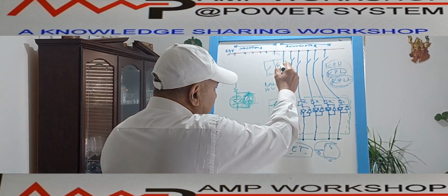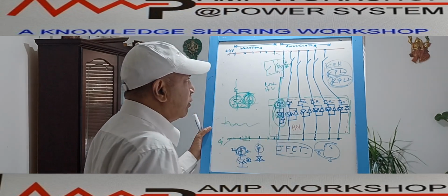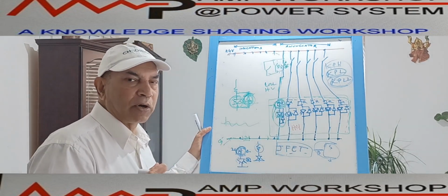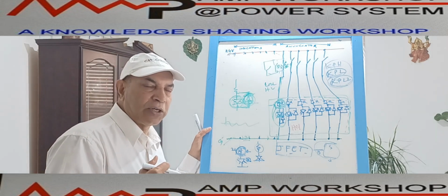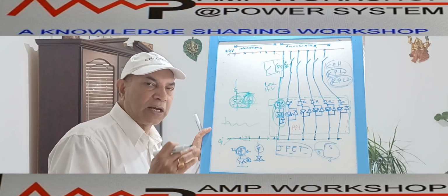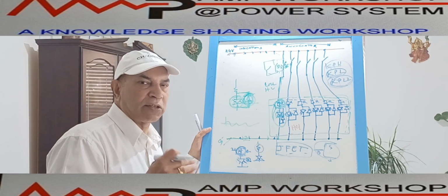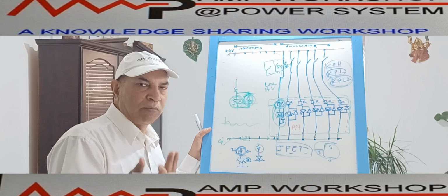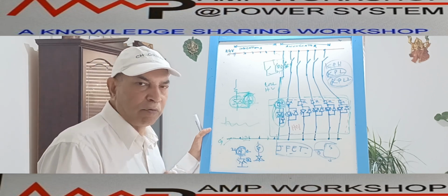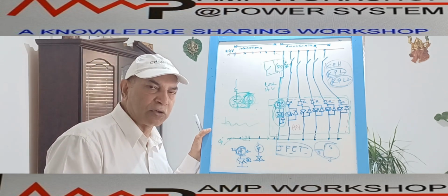So this is a lockout relay operated protection fault we monitor. This is one of the abnormal conditions. What could be the second abnormal condition? Suppose we are giving a control supply to the switchgear. I have already told about the various control supplies: 120 volt DC control supply, 24 volt control supply, maybe 48 volt control supply.